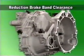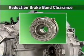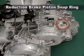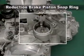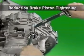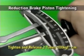When assembling the 5-speed automatic transaxle, adjust the band clearance of the band type reduction brake installed at the sub-transaxle. Next, install the reduction brake piston snap ring. Hold the reduction brake piston to prevent turning and tighten and release the adjuster rod 2 times with a tightening torque of 100 kilogram force centimeters.